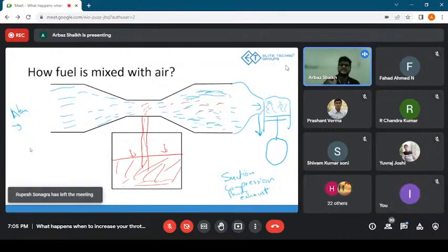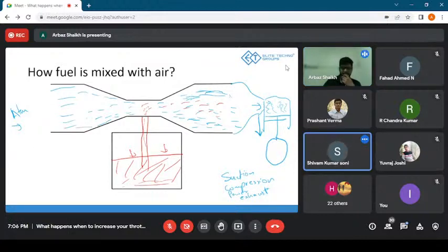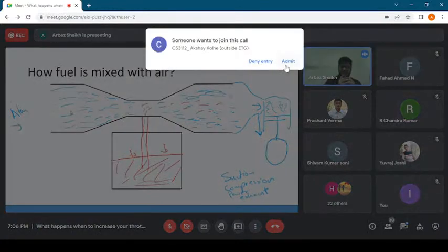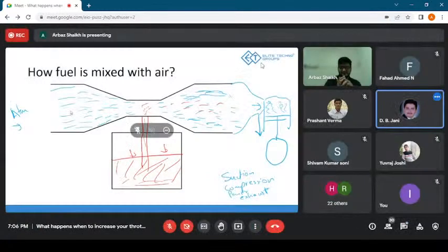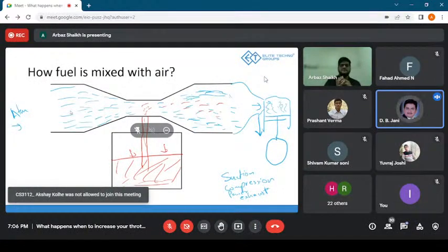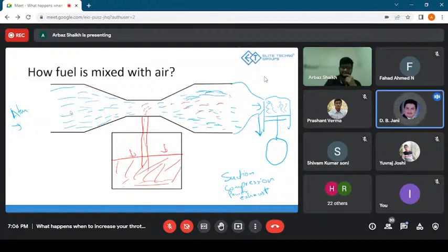Now, the main topic of the day. What do you think happens when you press the accelerator? You know the arrangement over here. What do you think happens when you press the accelerator? Sir, can you repeat the question, sir? Yeah, so what is the theme of today's webinar? What happens when you press the accelerator, right? What happens when you increase the throttle, rather? Throttle getting opened wide, so that more and more air will enter the carburetor, so that more pressure difference will occur, and so that more fuel will enter through the Venturi.